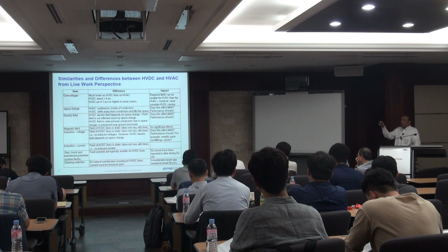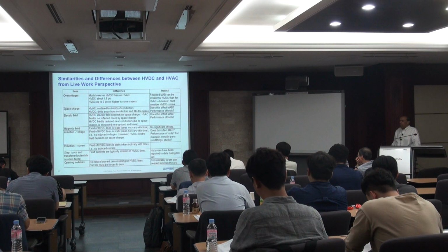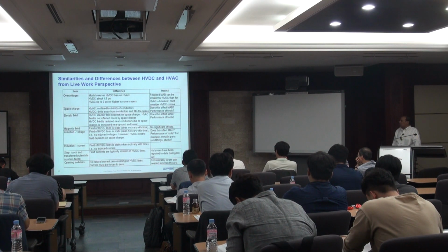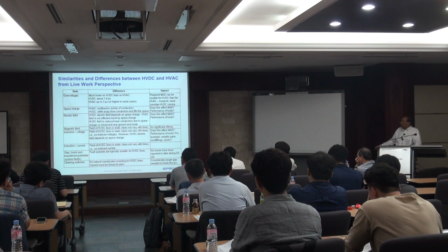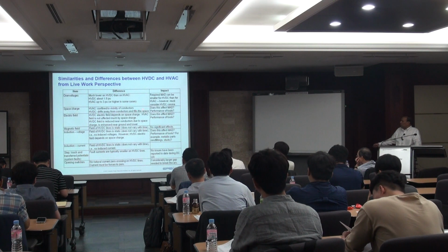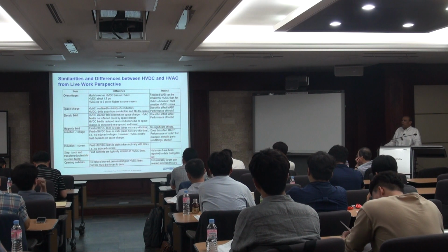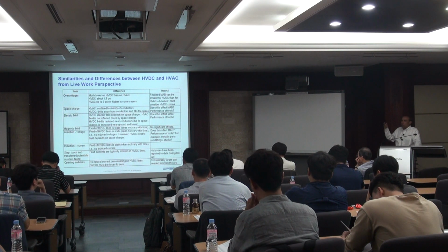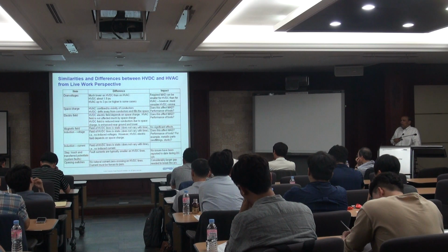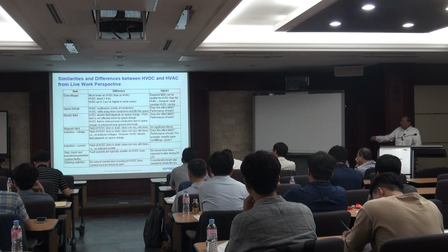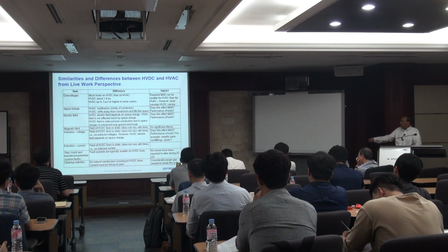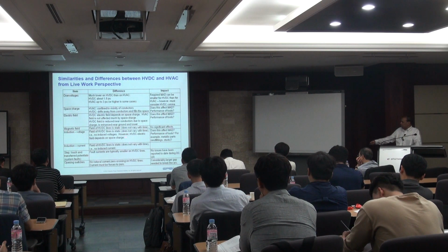How far does he have to be so that he won't have any problems or electrocution? That is the research we are doing, and the ultimate goal is to come up with standards for how far you should be from the live or energized conductor to do any operation and maintenance, or to change equipment or insulators. It also covers what kinds of issues arise for voltages, and how they affect AC lines versus DC lines.